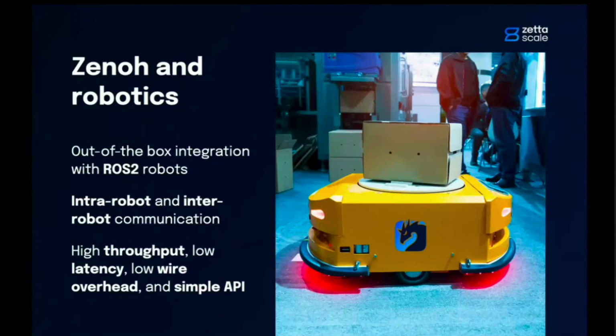We have seen so far Zenoh for inter-robot, robot-to-sensor or robot-to-cloud communication. But also, as a reminder, and as highlighted in the initial presentation by Angelo, in Zenoh we can also do zero copy. That means you can use Zenoh internally to the robot or to any device to do very low latency and zero copy communication between multiple components of your application.